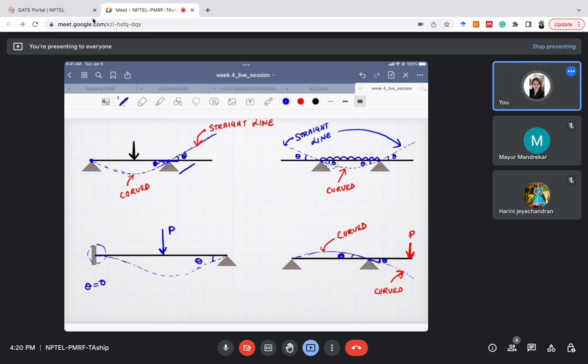So in this case, this is a beam, right? We will provide the main reinforcement in the lower part below the neutral axis, because the tension is coming on the lower part. But for this kind of loading, we'll provide it on the top part, because tension is coming on the top part here.